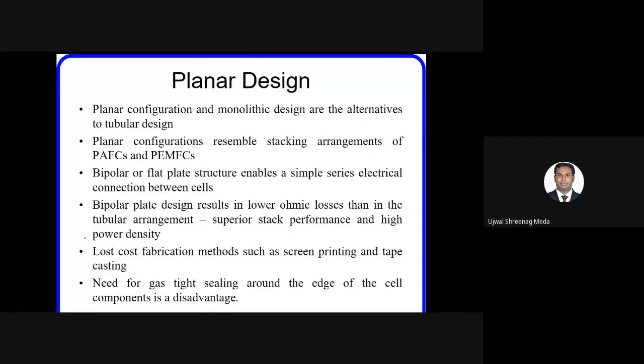And usually the losses that dominate in SOFC, as discussed, are ohmic losses. So in order to bring down those ohmic losses, the electrolyte is made as thin as possible. However, to compare between the designs, the bipolar plate design offers very little resistance. So the ohmic losses are low in the case of bipolar plate design. And stack performance is also very good, and power density is high.